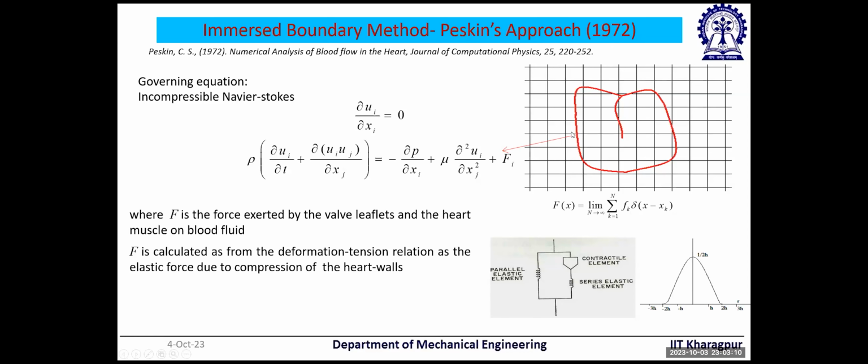complex moving deformable boundary by a set of Lagrangian points, which are immersed inside the Cartesian mesh. Then we see which are the Cartesian mesh blocks, or what are the nearest Cartesian mesh points of that unstructured set of points defining the Lagrangian solid boundary, and use a forcing function. This was first proposed by Peskin in simulation of flow over deforming heart walls.